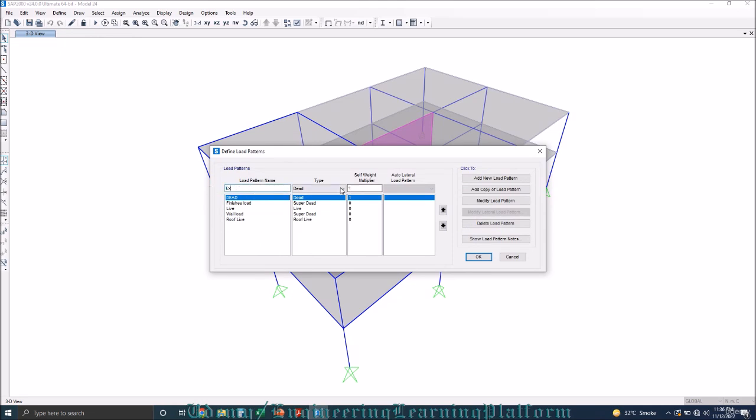Let's go to earthquake in X direction. In latest SAP, we have the load case defined as quake, but in previous SAP versions we have the load of the earthquake defined as seismic. So it's just a difference of the name. We'll select the quake option from here and select our loading code for the lateral load criteria. We have the loading code available as ASCE 7-16 here.